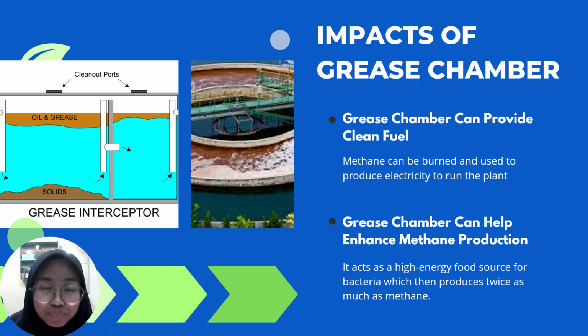wastewater companies. Scientists have also recently discovered that adding a specific amount of fat, oil and grease, or we can use the term FOGs, to the sludge in the digester provides a high energy food source for the digester bacteria and can produce more than twice as much methane. This means that the good bacteria can last longer to treat the wastewater and are effective in discharging clean water according to the standard.